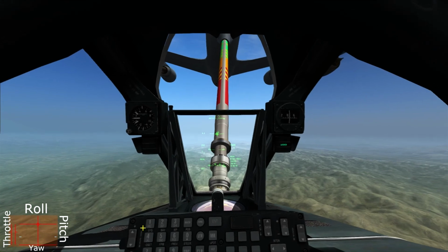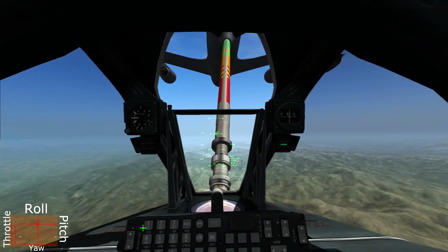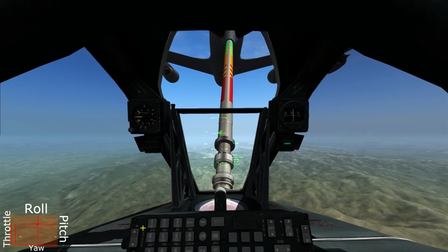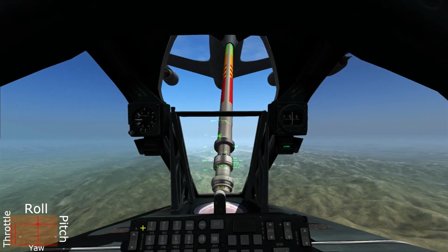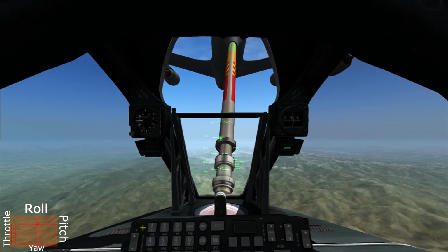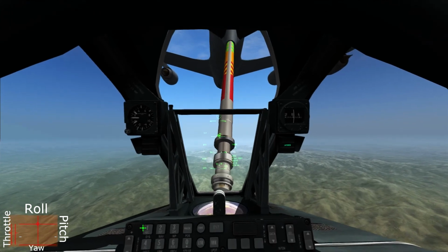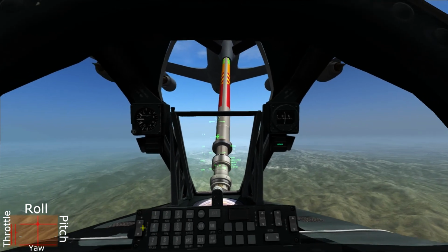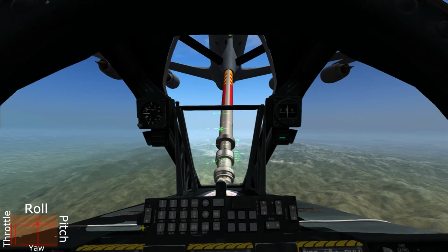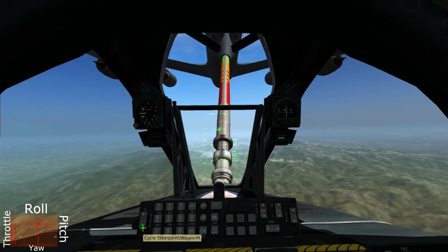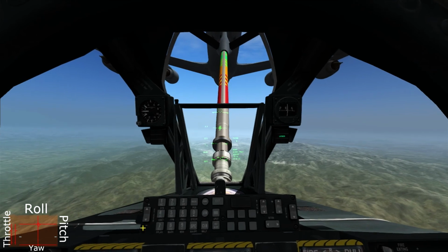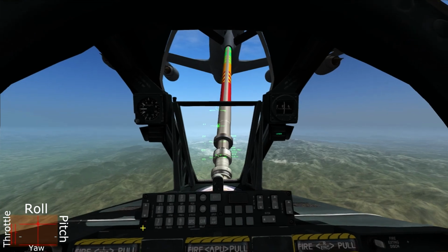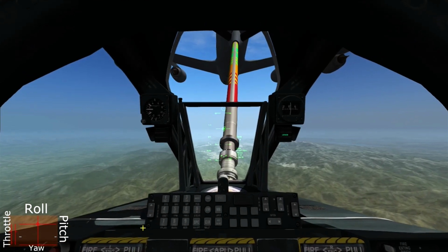In a minute, the tanker's going to go into a turn, and you can see how that's handled. The key is not to panic when he goes into a turn, and just to pretend that the tanker is the horizon. So you just ignore the outside world and just pretend the tanker is the horizon. We got too close and we dropped a lot of power, and then we immediately put the power back up to like the middle position. So we didn't overcompensate, and we're back on the green. This just takes practice to know where that middle position is for different speeds of the tanker.